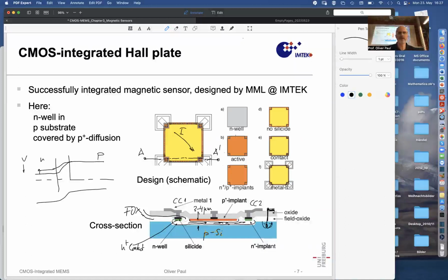So there needs to be a mask that defines oxide everywhere, and these little, how would I say that, belts around the contact regions. They are seen here. Then we need some N and P plus implants. I think we may need two masks here. Could be. So here, these N plus contact implants and this P plus contact in the middle.